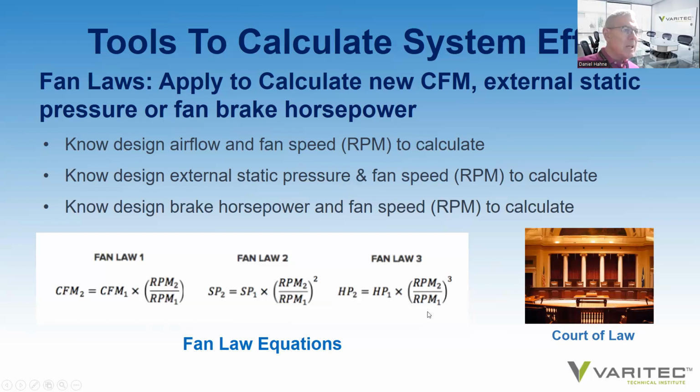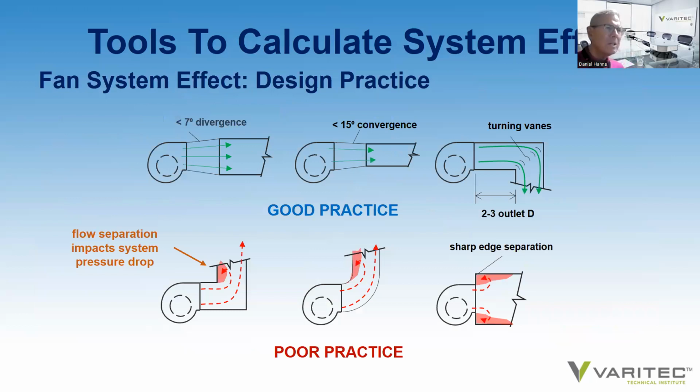Depending on how much static pressure gain, you may have to increase the size of the motor horsepower, which means you would have to look to see what electrical is available to service that horsepower, if it is available. And if it's not, that means you have to change out the electrical to that fan. So the dominoes start falling very, very quickly when duct configurations are not properly addressed or seen to, either in design or installation in the field.